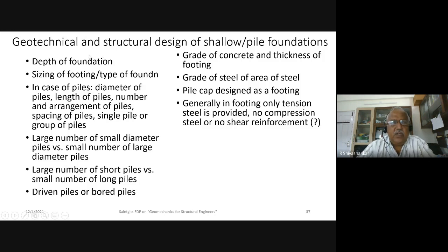When I say geotechnical design, I design the depth of foundation, the size of foundation, and the type, which can be isolated or combined or raft. In the case of piles, the diameter of piles, length of piles, the arrangement of piles, spacing, and group of piles.